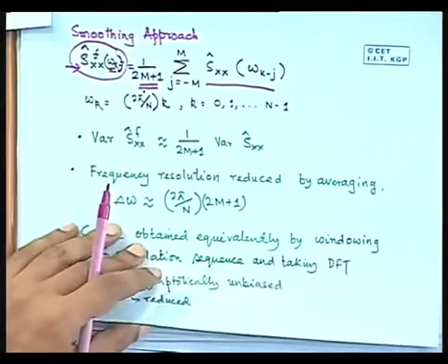What is the other approach? Here what you are doing is you are taking a data sequence, the whole periodogram you are computing. After you have computed it, from that periodogram you are doing averaging on the frequency axis. Rather than that, you can do what is known as a sort of virtual ensemble averaging. That is, not do an actual ensemble average. You got a long sequence, so I will chop this sequence into smaller time sequences. Out of one long sequence, let me make 10 small sequences. Then corresponding to those 10, I can make 10 periodograms, and once I calculate 10 different periodograms, I will simply average them. That is something I can do.